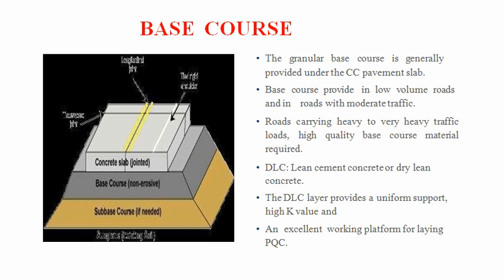The dry lean concrete layer provides uniform support. It has a high K value and is an excellent working platform for laying the PQC.